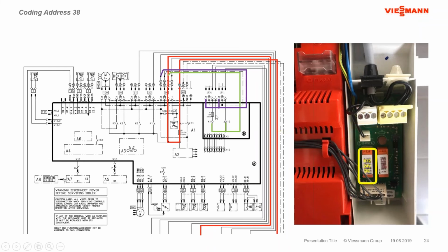So K11 and the K12 relay are part of the circuit board here, and they need to close for that power to move past the K11 or K12 relay contact. And what switches those is a 24-volt DC contact. That 24-volt DC is actually coming from the control.